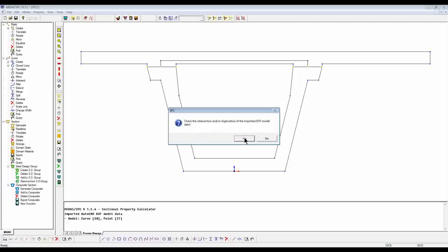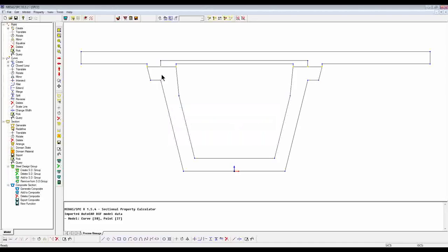Say yes. The purpose of this one is because in case there's any duplicate lines from the CAD, is to make sure all of them are disconnected and the duplicate members are gotten rid of. So those little steps that I just highlighted, they are something that can really affect your CAD drawing import.